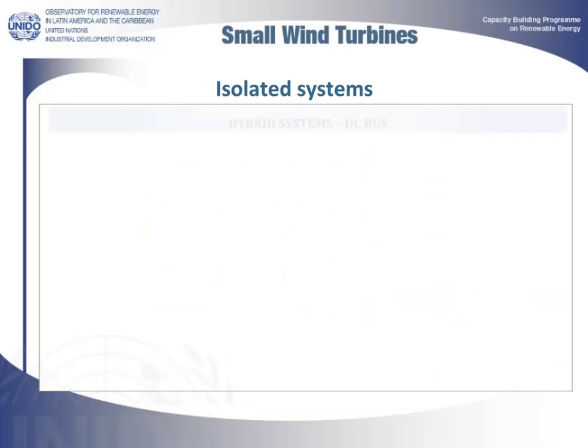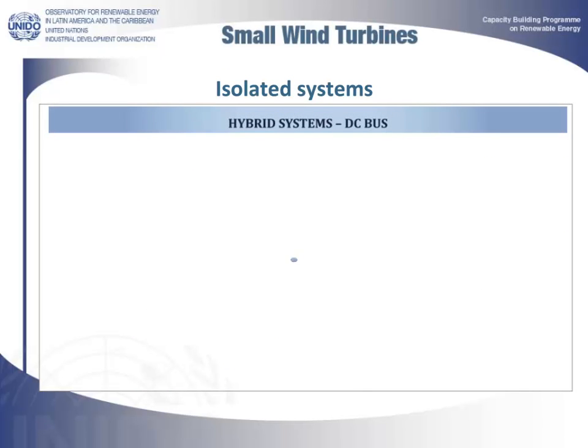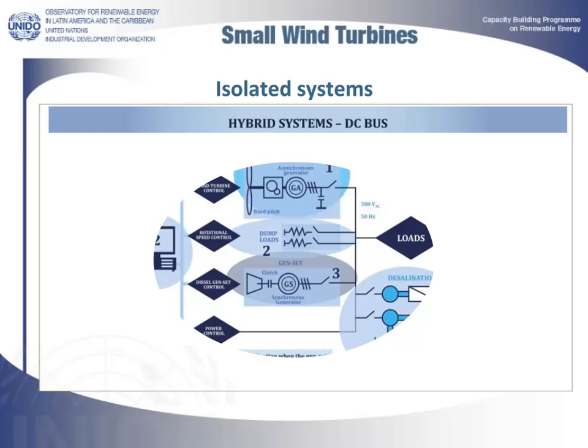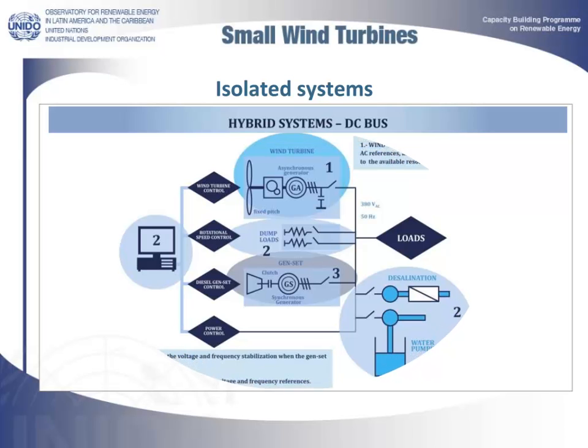In these systems, batteries play a fundamental role. Apart from their evident role as energy storage systems, they also act as voltage regulation systems. The other components, wind turbines and/or photovoltaic generators, are adapted to the voltage imposed by the energy balance at the battery terminals. The presence of wind and photovoltaic controllers is explained by the need to protect batteries against overcharging, while protection against over-discharging would be a function of the inverter.